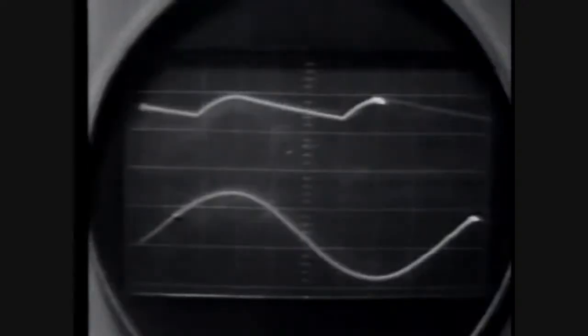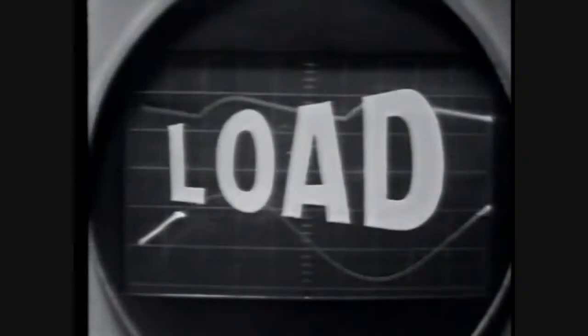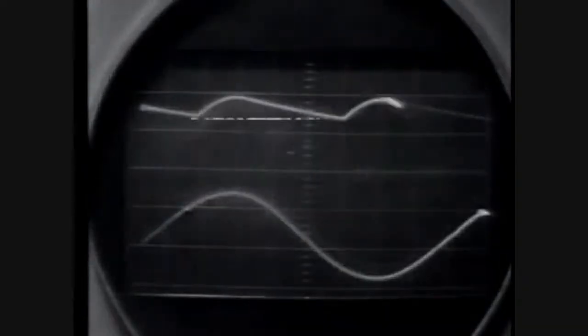The load on the circuit also affects ripple amplitude. The greater the load, the longer the diodes conduct, and the greater the ripple amplitude. Ripple amplitude, therefore, is dependent upon the value of the load. Ripple frequency remains the same, twice that of the input. However, as ripple amplitude increases, filtering becomes more difficult and average voltage decreases.